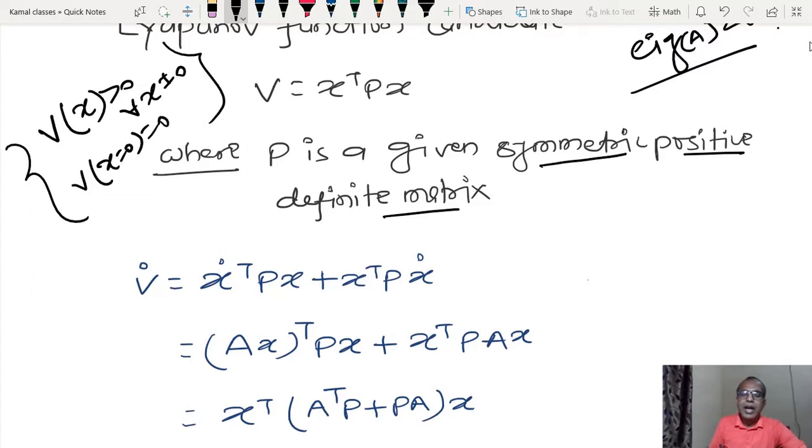No, sir. And one more important thing: whenever you are going to construct the Lyapunov function, please be careful, all state information should be there. If you miss some state information, it means that you do not care about the energy associated with that particular element.